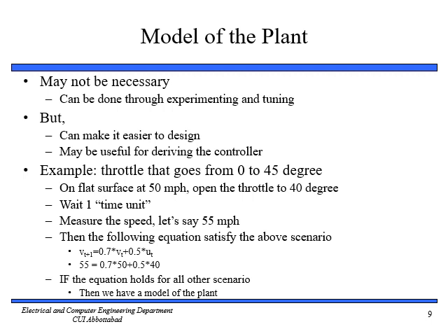In many cases of controller design, our first task is to develop a model of how the plant behaves. A model describes how the plant output reacts to a function of the plant inputs and current states. For our cruise control, the model should describe how the plant reacts to the throttle position and the current speed of the car. As we will see later, we do not always have a model of the plant, and instead could design a controller through somewhat ad hoc experimenting.